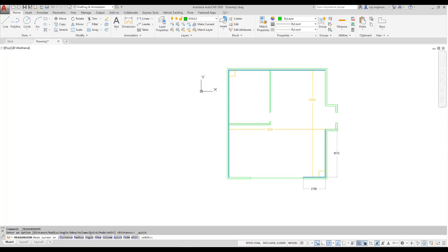So we can see there the width, interior width is 10.2, and the external width there is 10.5, and what they're 9.5, so we can confirm that we've got the exterior dimensions correct. And there's our interior dimensions. We're happy with that. Let's have a look at our little area in here. Put in there, there's 1000, there's the wall width of 150. So the quick measure tool, very handy to verify what we've drawn.